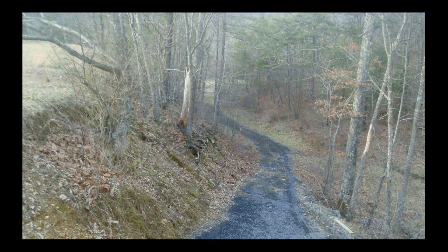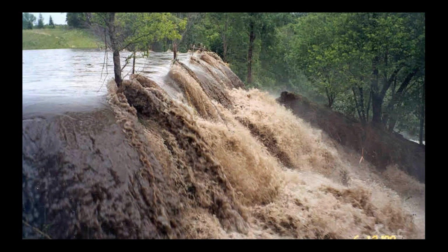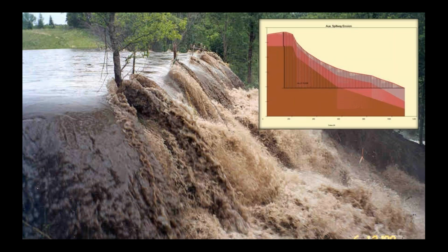Well, what would that look like if that flow was going through the spillway? Let's imagine a 100-year plus flow, and it would look like this. This is a whole lot different. The flow that's going through here, this is what the spillway was designed for, this type of flow. But at the downstream end, we have a lot of energy being dissipated. We're essentially going from an armored slope to a head cut that's pre-existing because of the cut in the road.